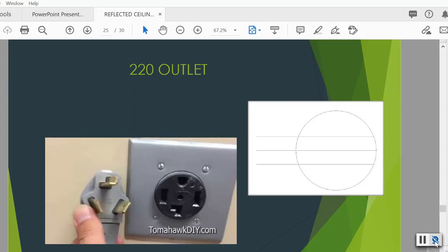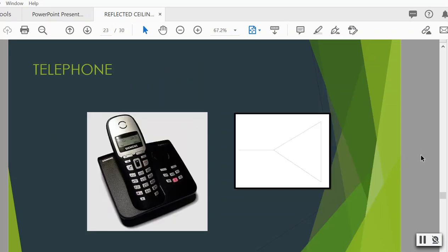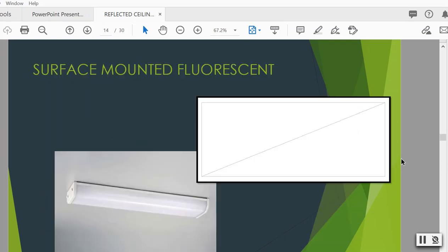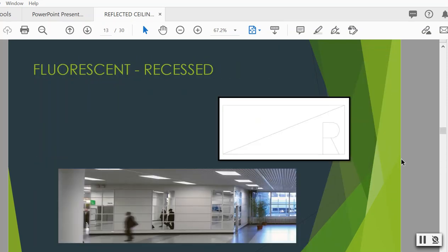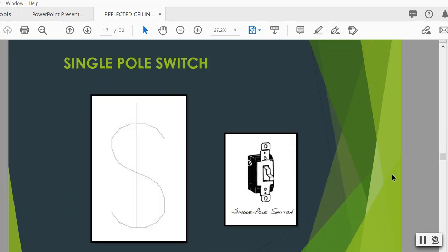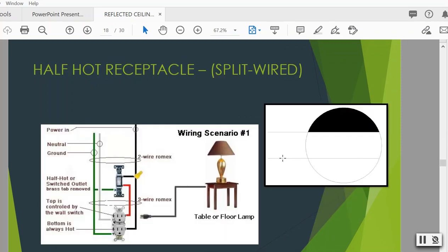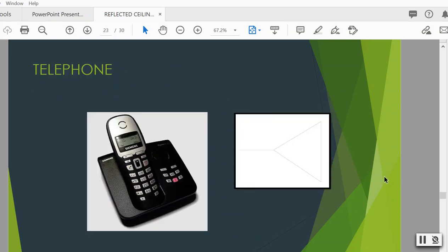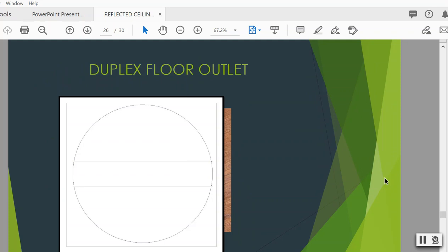So make sure when you're designing a kitchen, you know where every appliance goes, so you can make sure you have the right outlets for those appliances. So that's a 220 volt. A regular outlet over here, as we saw, is considered, let's go back at it. Maybe I went too fast trying to find that regular outlet, but these are 110 volts. They're just a regular outlet.